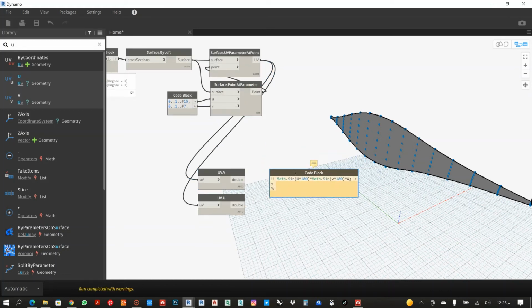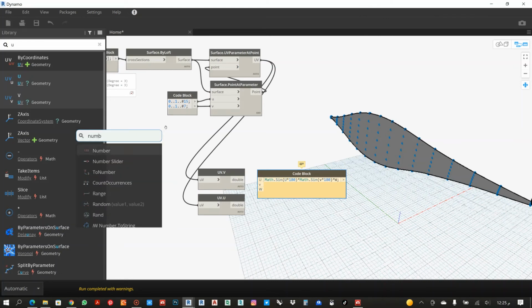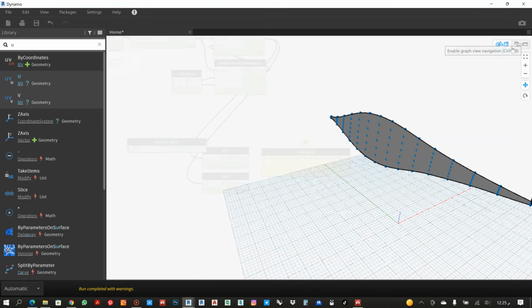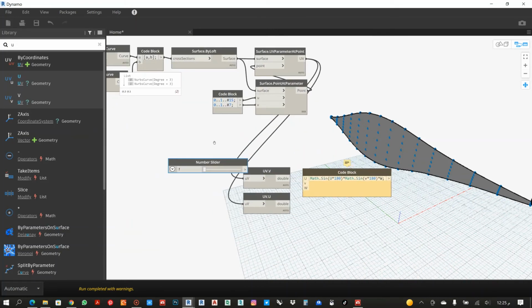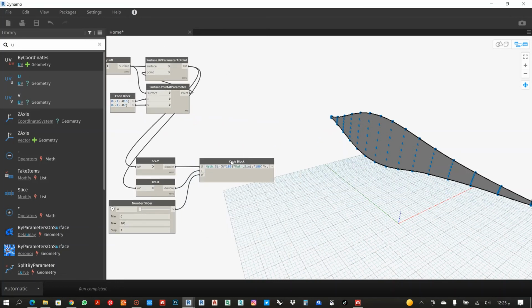And let's say this is my equation, and I will make a number slider, with steps of one. Here now I will connect, let's propose this as 4, and I will connect my u and v and my value. Now this value shows me how I need to make my curve, in which way to transform the points to other points to make this curve.